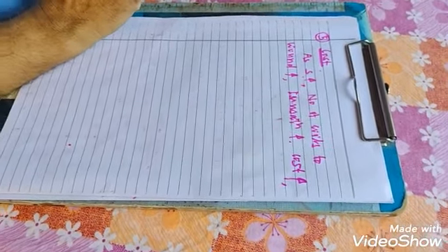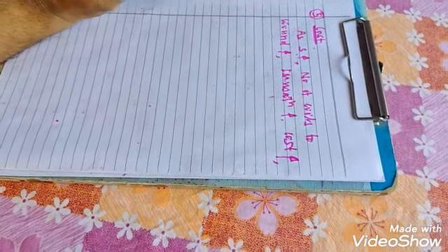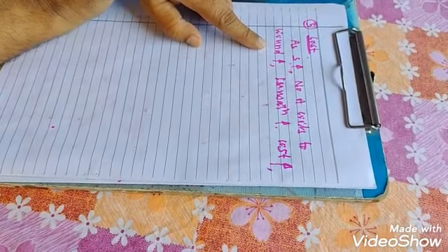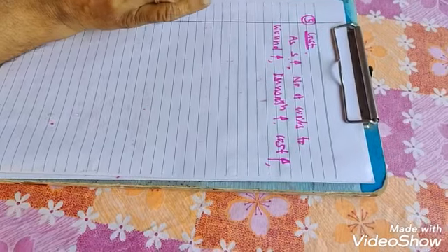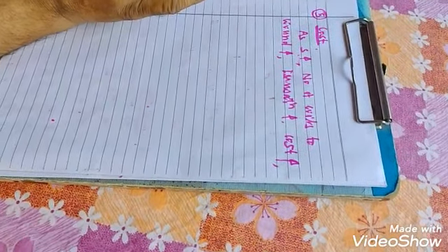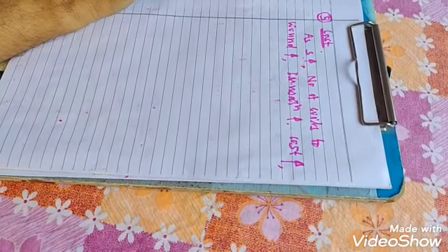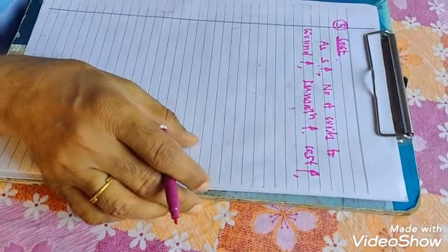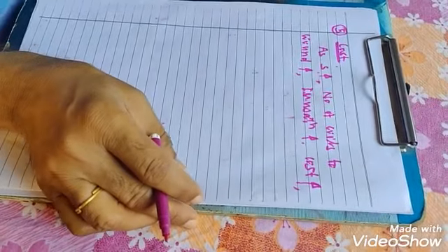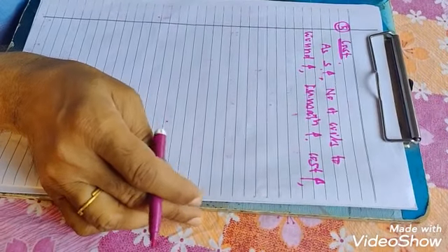At the same time, the number of coils to be wound is increasing. We have to punch more number of slots. Therefore, the labor cost of punching the slots and winding the machine increases.